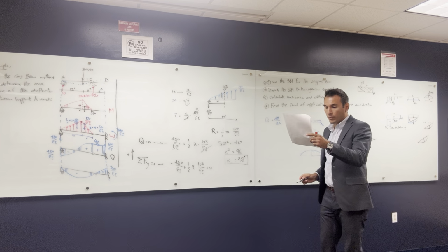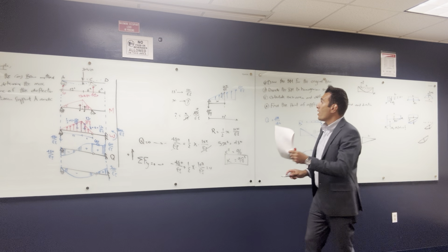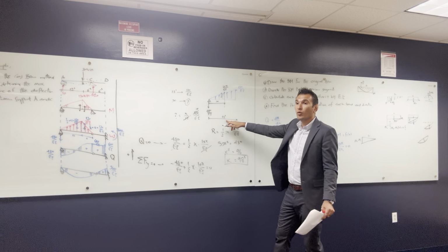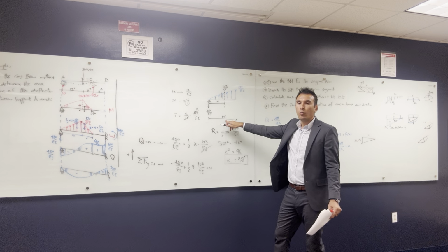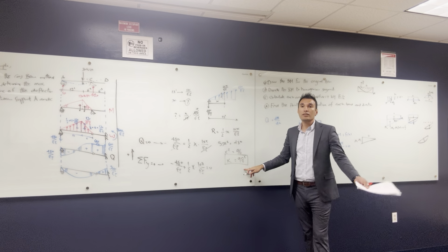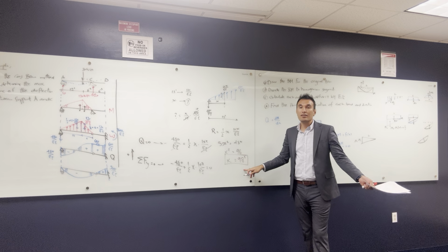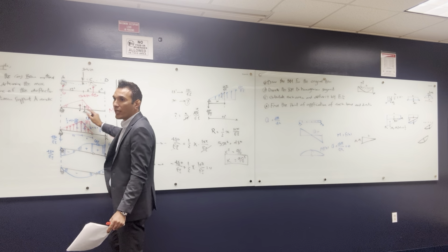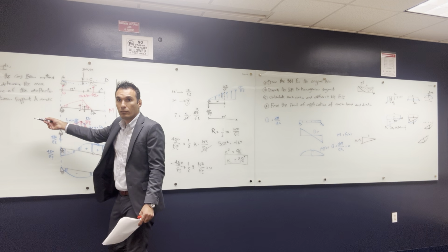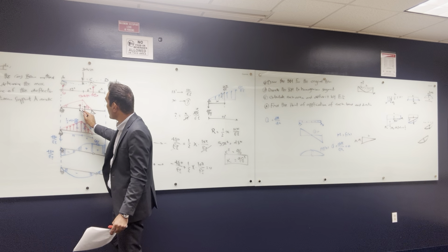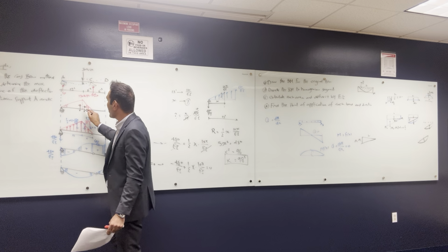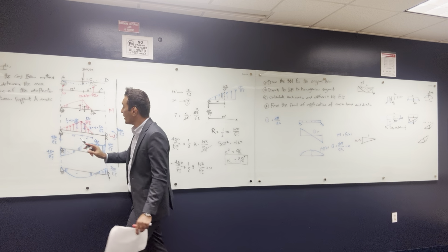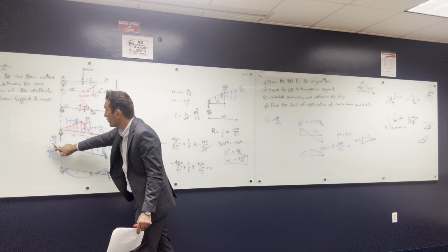Okay? So, if this is 9.8 feet, which means it's less than 12, that means our assumption is right. But what if you get the value of this 13 or 14? That means our assumption is not right, and we need to get the other triangle in the equation. Okay, that means that the point of the 0 is not in this triangle, it's in the other triangle. The value of this triangle is not enough to counter the shear coming from the reaction.